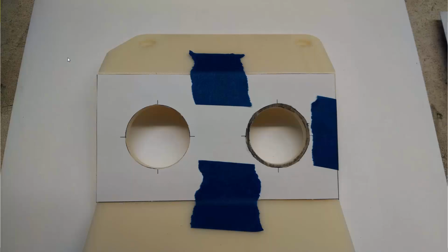So this is what I did. I changed the model, printed out another one, a scaled 1:1 drawing. I taped it onto the part. I marked it with a marker, and then I used my Dremel to just grind it to size. So it wasn't perfect, but it got me to where I needed to be in this prototype.